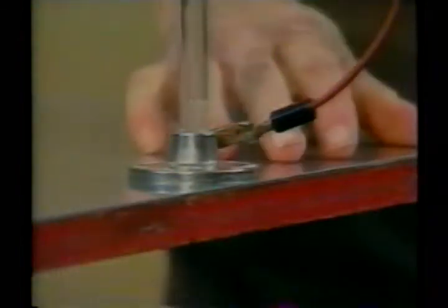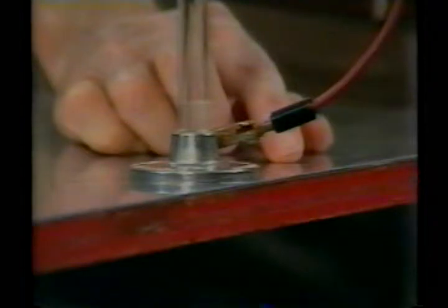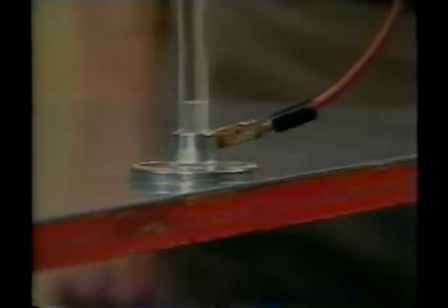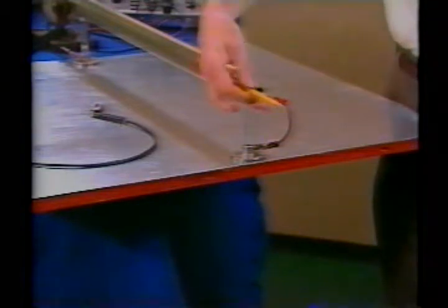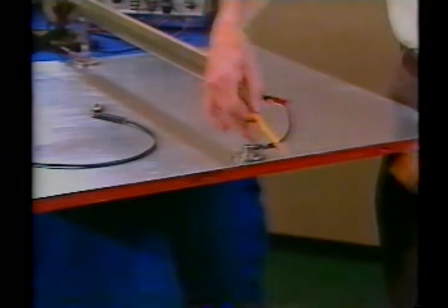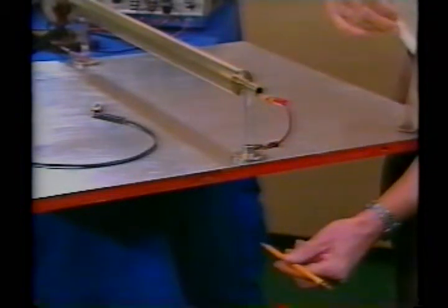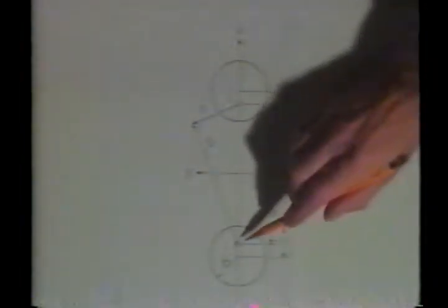The value of A is just that for which the cylinder of radius r has no perpendicular component of magnetic field. These are the field lines produced by the line currents. The field is tangential to the surface of the cylinder and to the midplane. Thus, these surfaces can be replaced by the metal surfaces of the cylinder and ground plane.